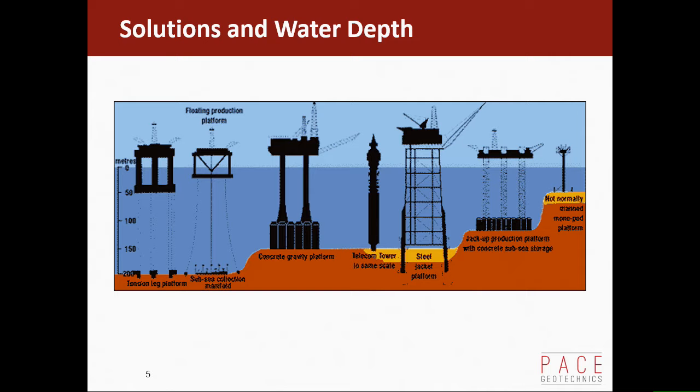And then you come to floating solutions, which don't actually sit on the seabed, but are anchored to the seabed in some shape or form. That's where on deep water developments you're most likely to find suction piles, as well as supporting seabed structures. In shallower jobs, where the geology tends to be harder, you're more likely to have a driven pile solution, so just a tubular steel pile driven into the seabed with a mooring chain on it, and that stops the floating production unit, the ship basically, drifting off station.